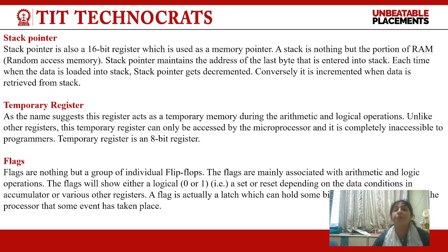As the name itself suggests, this register is used for temporary storage of data. It acts as a temporary memory during arithmetic and logical operations. Unlike the other registers, the temporary register can only be accessed by the microprocessor, and it is completely inaccessible to the programmer. The temporary register is an 8-bit register.